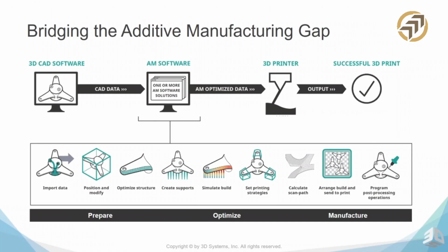It is a good opportunity to mention that the manufacturing workflow doesn't end with the printer. There is a set of post-processing actions that we need to perform before getting the final part. And we better take the post-processing considerations into account as we do our design to print. For example, taking into account the impact of the part orientation during the print on the surface quality, which might require additional extra work of polishing to get to the desired quality, or manual work to remove supports, or even leaving holes to be able to remove the powder from hollowed volumes.